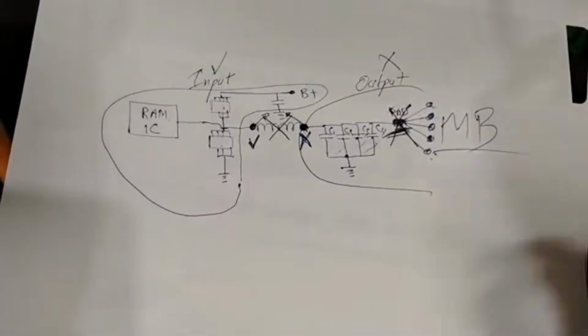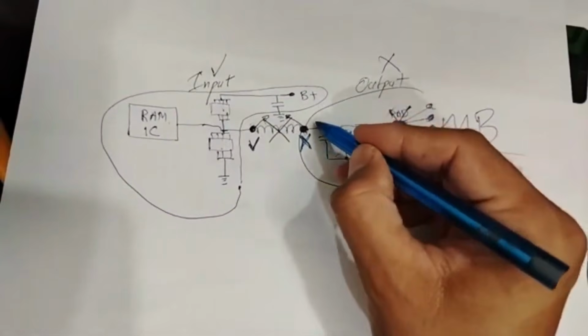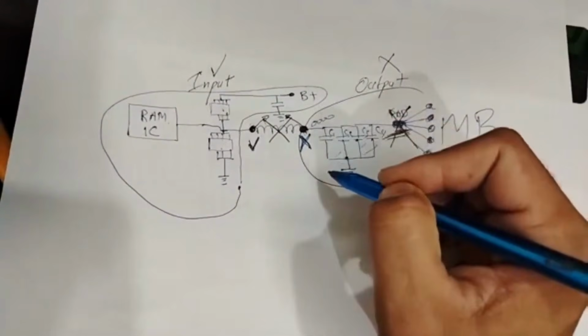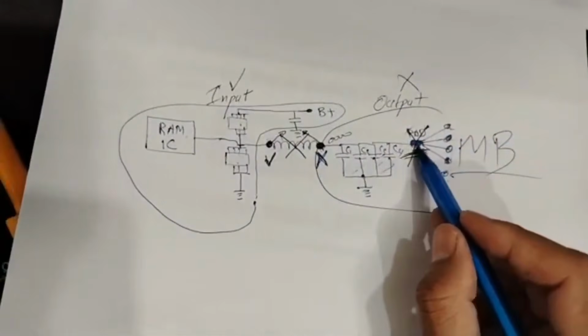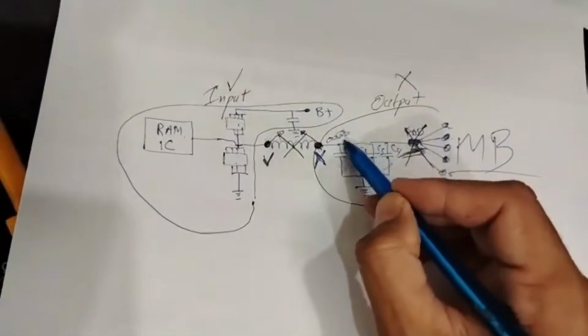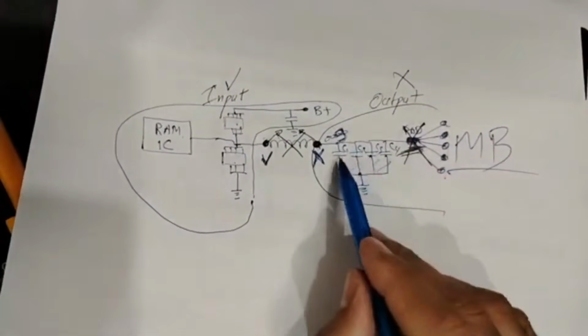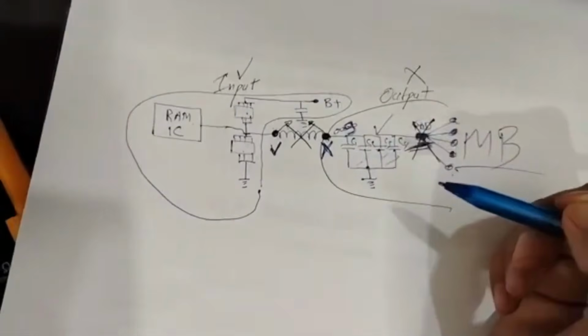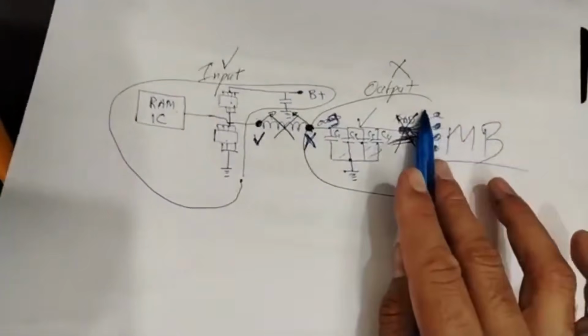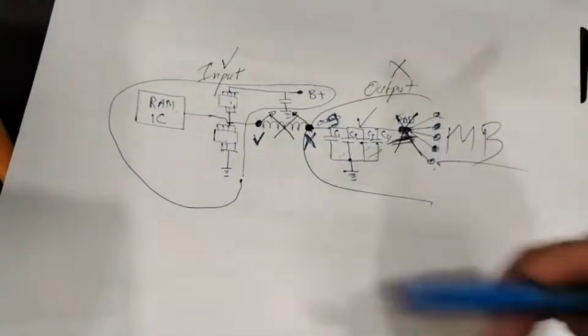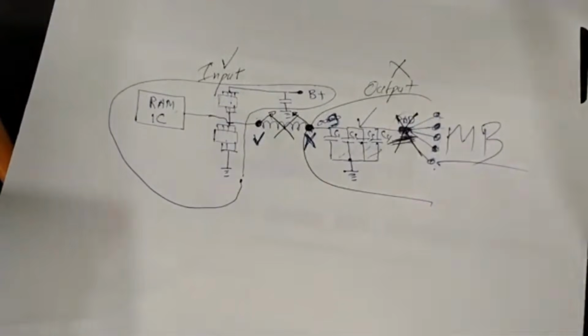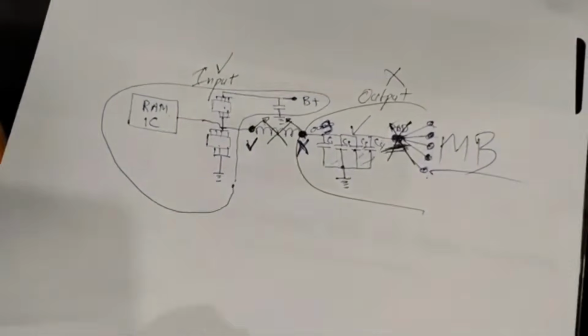Guys, I find here using the multimeter 0. But after removing the pad, I find 0.9. Like this, reading. Means the ceramic capacitors are good. Means the short is in this side. Let's find out if this is right or not. How? I show you how.